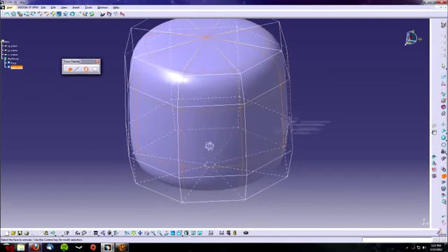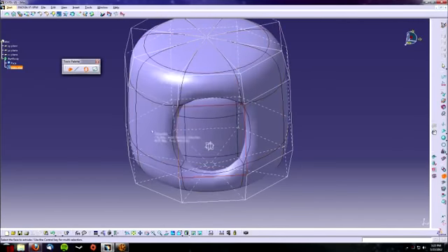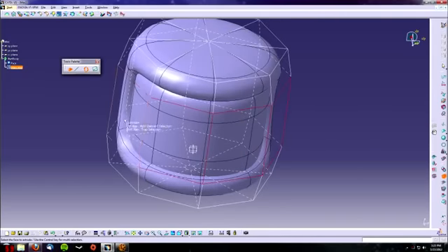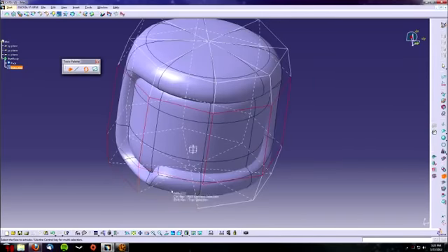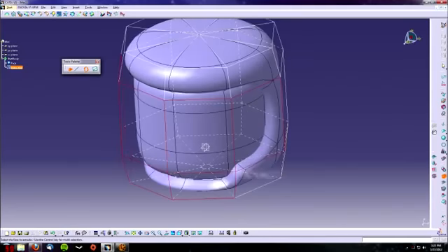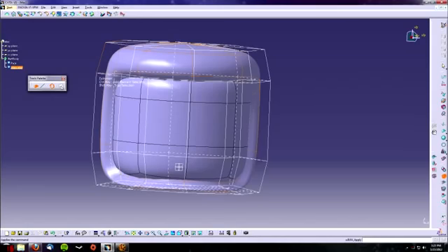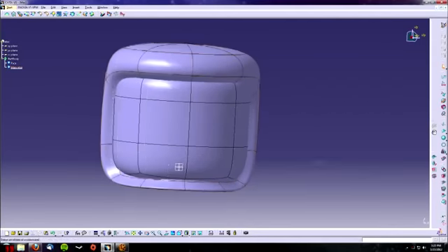Be sure when using the extrude command for his face, you click on the little invert button. It looks like a pair of circles going around a circle. Use that and click on the front features of his face so that you can actually pad out, actually remove what's going to be where his face is going to be.